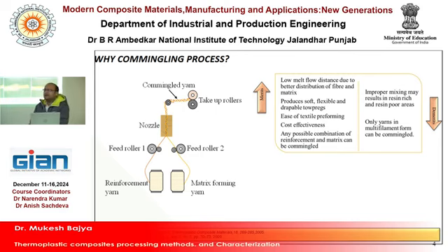Now I am coming to the characterization part. Whenever you are making the preforms, you need to confirm whether it is really happening or not, whatever your thought process. So then you will definitely go for optical microscopy, either seeing the cross section or the longitudinal view of the filament.